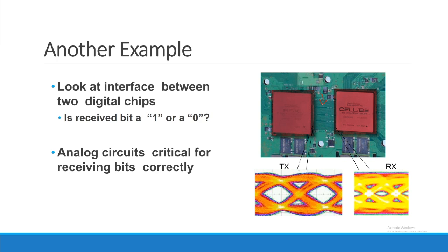So obviously the purpose here, at least on the receive side of one of these things, is to figure out, were the bits that were transmitted on the other side 1 or 0, okay? And as we're going to see later on in the class, because this is going to be our driving example, if these are the shape of the bits that I sent at the transmit side, by the way, this is called an eye diagram. Literally all I did was take all the bits that were transmitted and fold them on top of each other in time. Okay, so if you had something that was really perfect, you'd just see things that look kind of square like this.